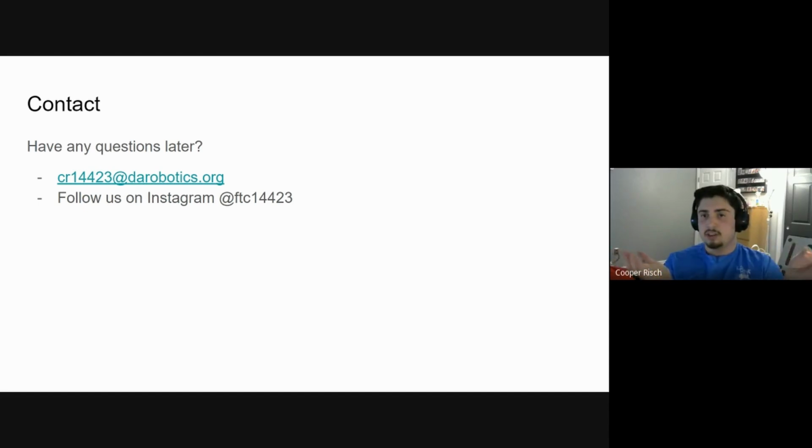And so what's great about doing stuff with 3D prints, especially as someone who's new to this, is you don't have to waste money investing in a complex metal part that you design just for it to break. But if you do a 3D print, you can track your progress using graphs and data and really see, is the stress too high with this further removed model? And then when you actually make the model, you can test it and see, hey, is this what I expected? Or is this not what I expected? Should I go back and try an older version, something that had less material removed? So I say just track each step as you go and make sure that you know the capability of each step.